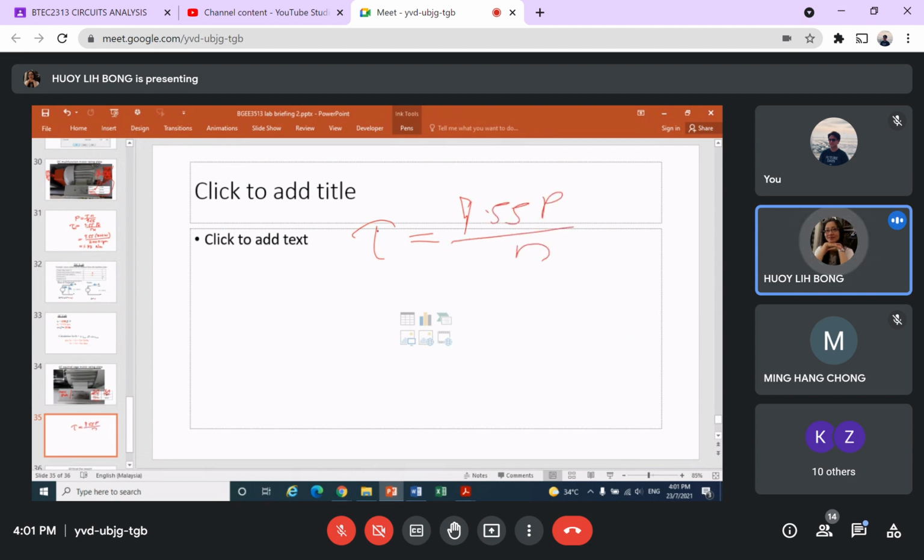Okay, but this torque, after we determine, actually is for delta, because we are actually operating at 400 volt. So this 400 volt actually is for delta. If the star also operates at 400 volt, what will be the torque for the star?